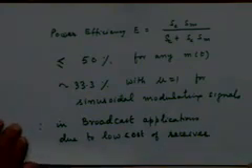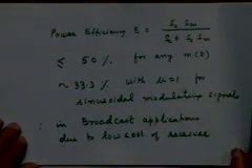Okay. So what is the alternative? There is no alternative. Alternative is to go for DSB-SC. But how would you make the carrier? Can be done. It's not undoable. All that I said is it's more complex. So if you agree to pay the cost for that complexity of the receiver, you can do it. It's not undoable. It's perfectly doable.